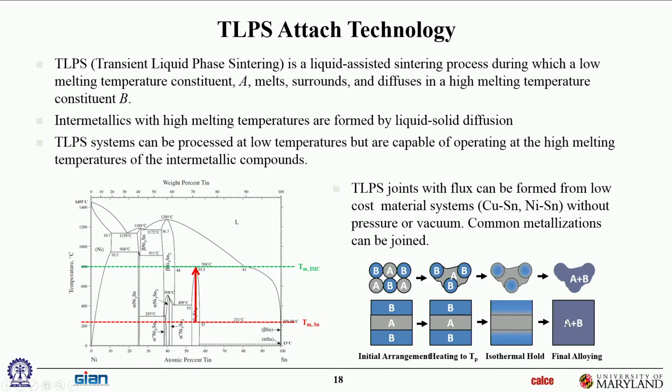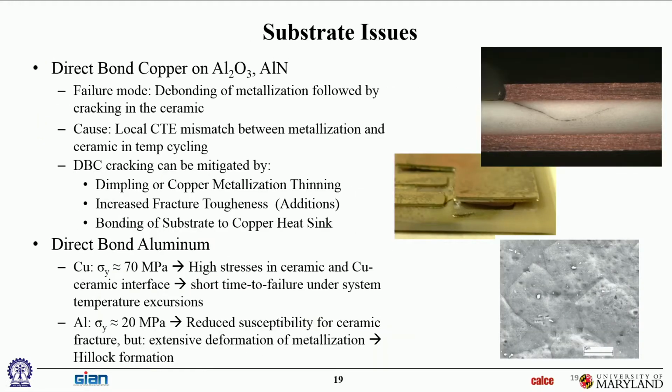Well, it won't be lead because lead is banned, but materials like that, ductile particles embedded in it, so that gives you toughness. So cracks that start to form will get arrested by those ductile particles and won't propagate all the way through. So that's the next generation TLPS that people are exploring. That's the overall concept. I'm not going to get into any more detail because that would take a long time.